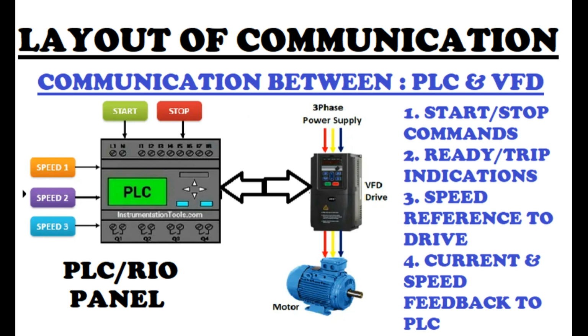So here we can see the communication between PLC and VFD, that is start stop command, ready trip indication, speed reference to drive from PLC, and current and speed feedback from drive to PLC. So all these four parameters we'll see one by one.